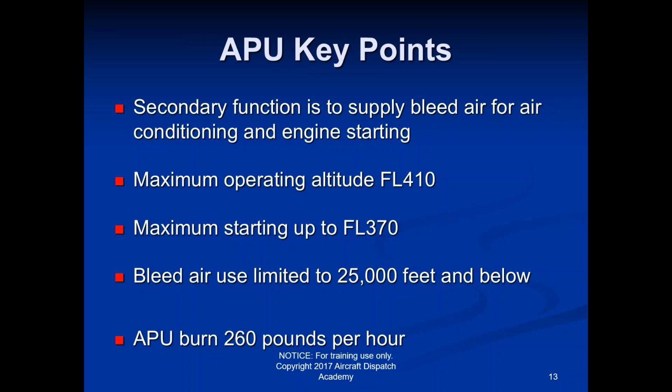They don't turn on the APU again usually until you're landing. So part of the landing checklist is to turn on the APU. So typically the only time we use the APU is just when we're on the ground, without engines on. So if you think about it that way, it's a little bit easier.